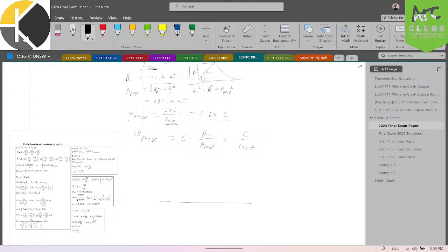Here is your pulse. Instead of going straight, it's going to travel here, and then reflect backward. The average speed of this pulse in the waveguide is going to be smaller than the speed of light. Actually, V group is just going to be c times cosine theta. It's going to be smaller by the same factor.